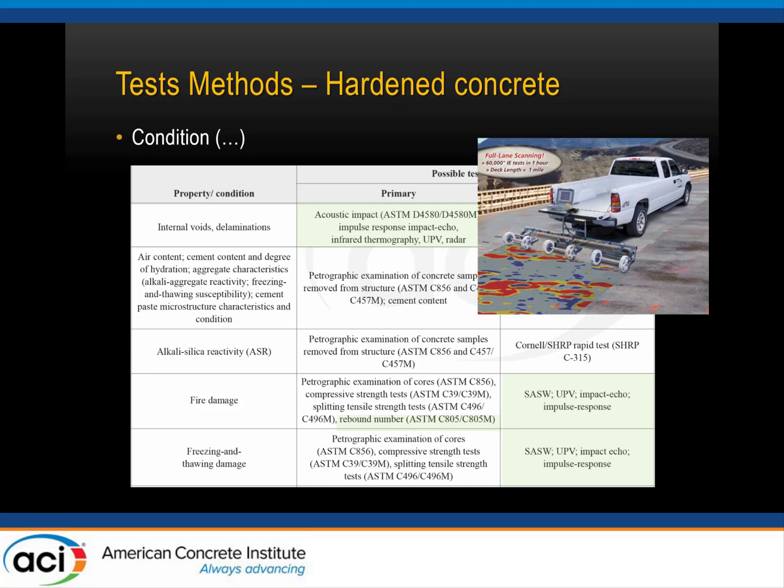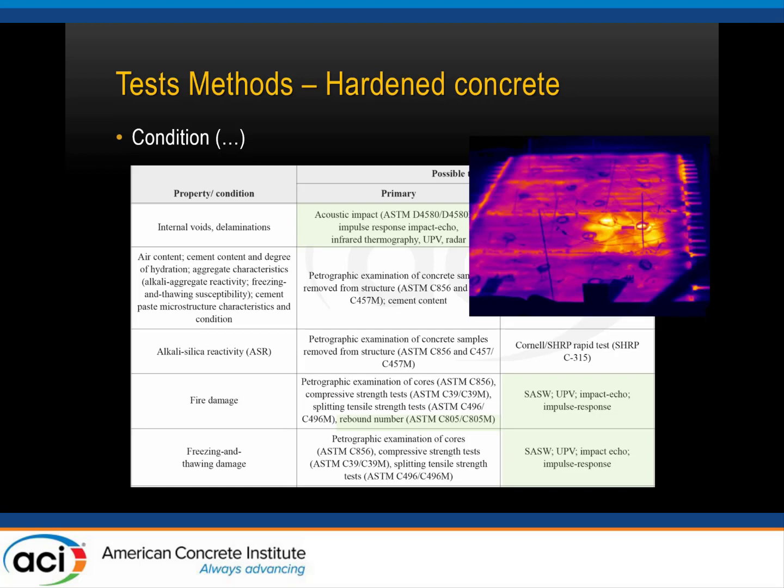There are tools that have been developing on the NDT side. For instance, this is the georadar that is used very effectively to sound large surfaces and evaluate the presence of defect, delamination, and so on. There's also thermography, another technique which can be used very effectively on certain types of structures, in certain circumstances, to supplement the actual sounding of the surface that we can perform with simple tools.